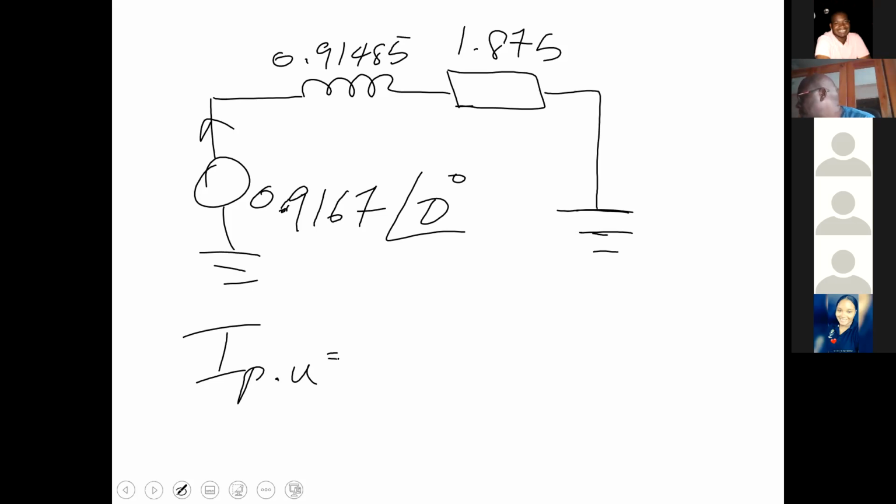So we can go to the slide before that, please. Anything you missed, just go back to the recording. We're running out of time right now. We are up to 10 minutes to 6. So you calculate the per unit current. Whatever you get for the per unit current, it will be the same current through all the network. What you will now need to do in finding the actual current in any part of the network is to find the base current.